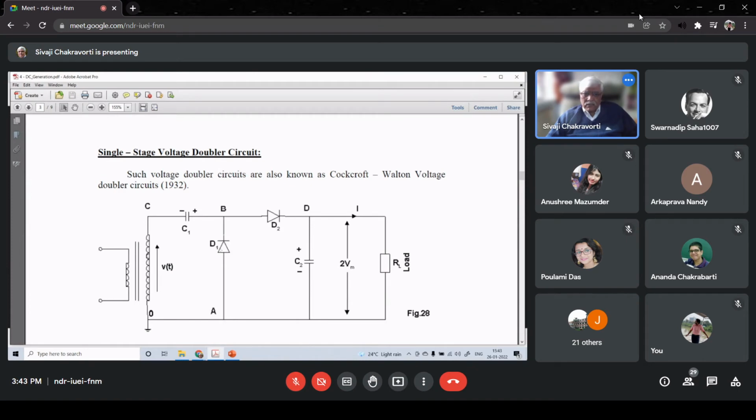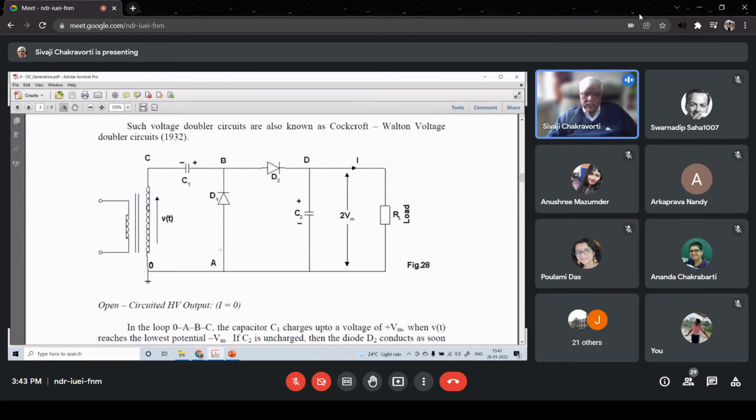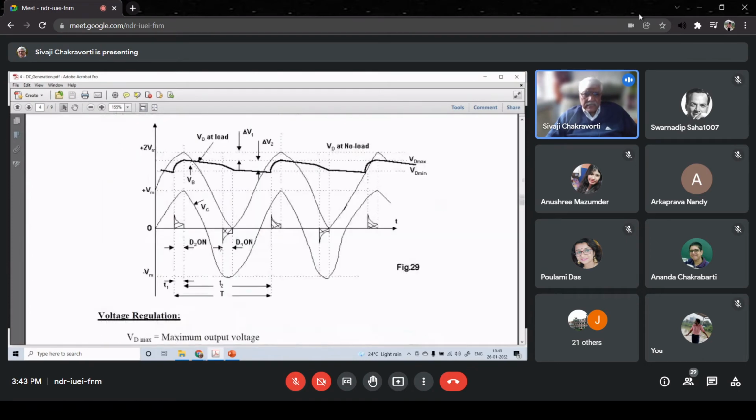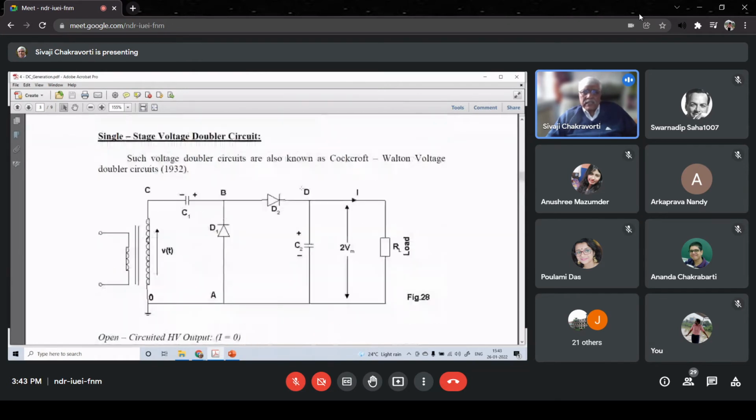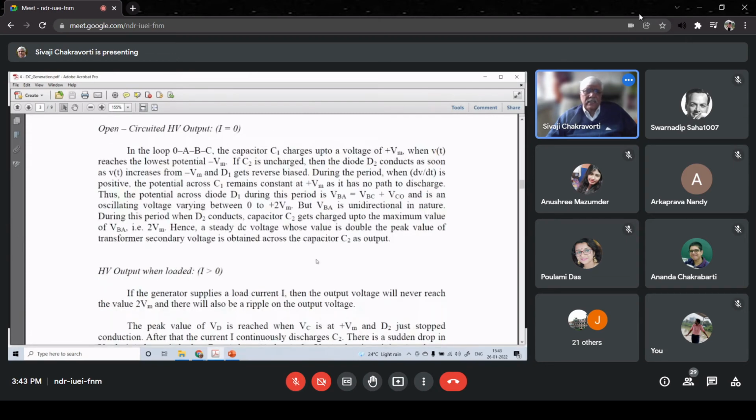But now, when D1 is conducting, for a small time before theta equal to 90 degree in this negative half cycle, it has only the reverse bias resistance of D2 on the left side of C2. So now D2 and RL come in parallel, and therefore there is a sudden drop in resistance parallel to C2, and therefore the time constant changes.